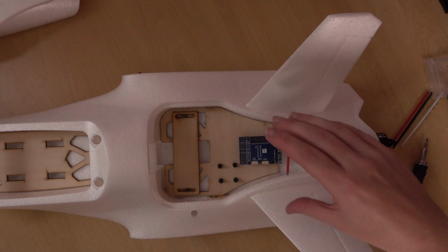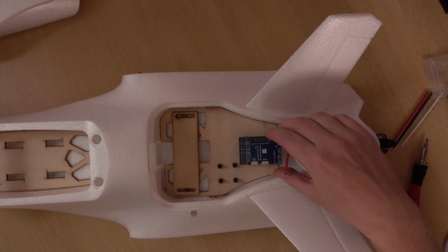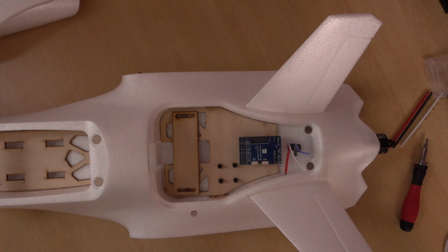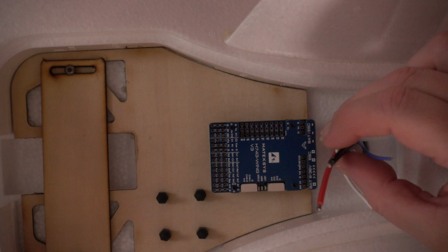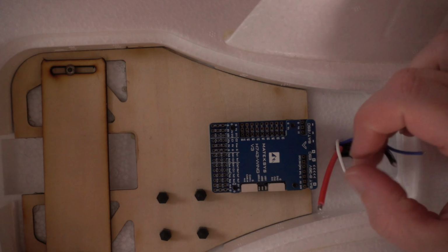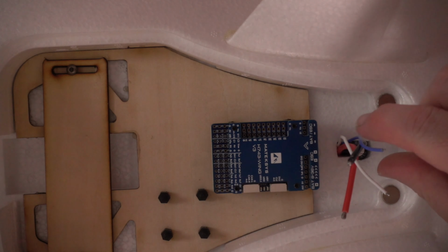So knowing approximate positions for where things are going, we can actually confidently start putting together things for the flight controller. So the next thing for consideration is how we're going to connect things to the flight controller. With this here, this is actually going to be a pretty simple setup. The ESC will solder directly onto there for the main power. We've obviously got our capacitor down here.